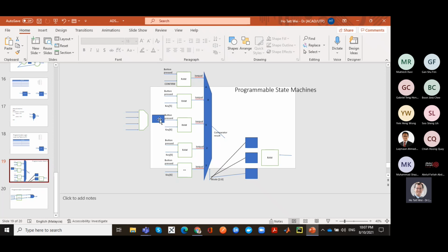So this is called a load and store architecture, because what you end up doing is you end up loading memory with a lot of different inputs, or the output could go back into this storage here, so that it can be reused or selected flexibly to go into any of these. So it's a load store because you load here into the memory, and then you store into this memory, and then you load it out into the compute units to do the processing.